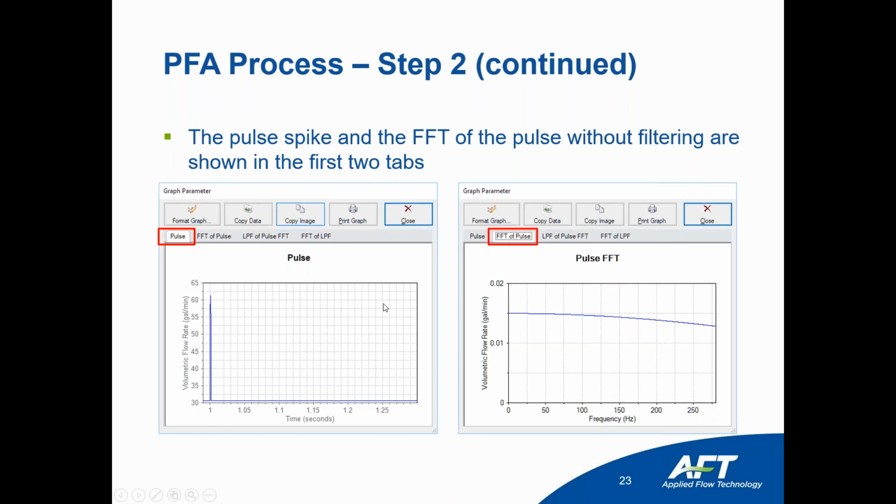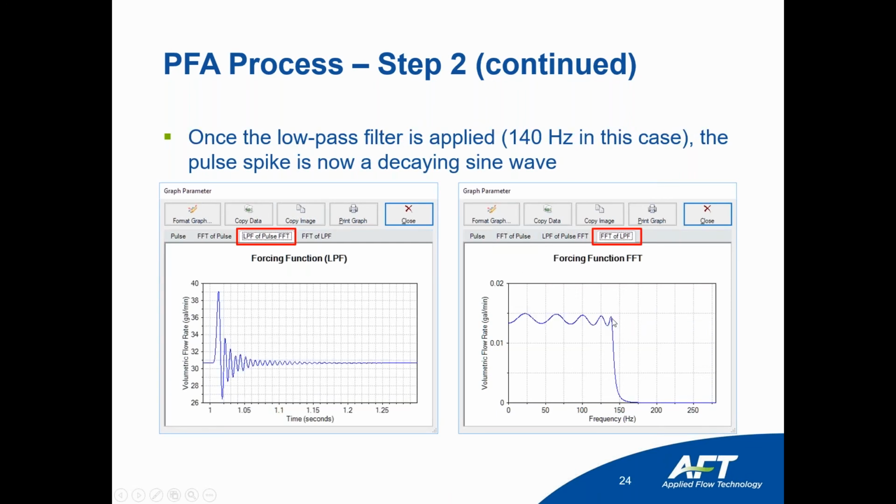So these pipes are the bottles, so you don't need to analyze them. And this pipe, P10, is isolated by the centrifugal pump. So this pipe here does not need to be included because the system that you're interested in is the suction, and you don't want to include this pipe in the system.